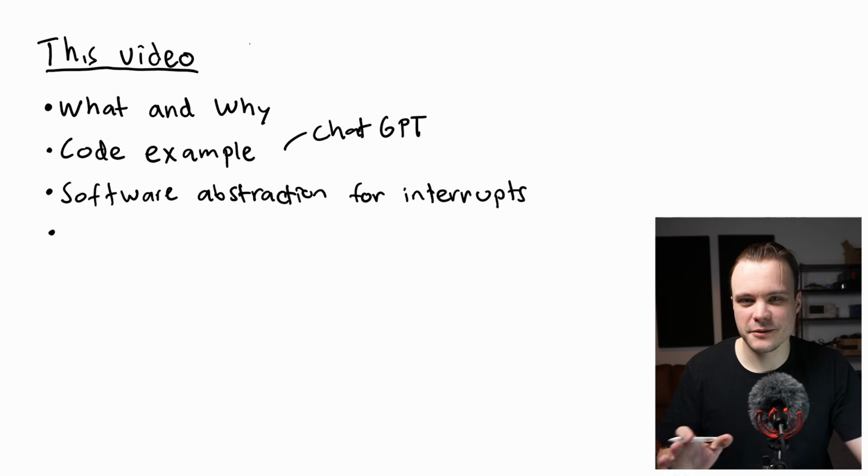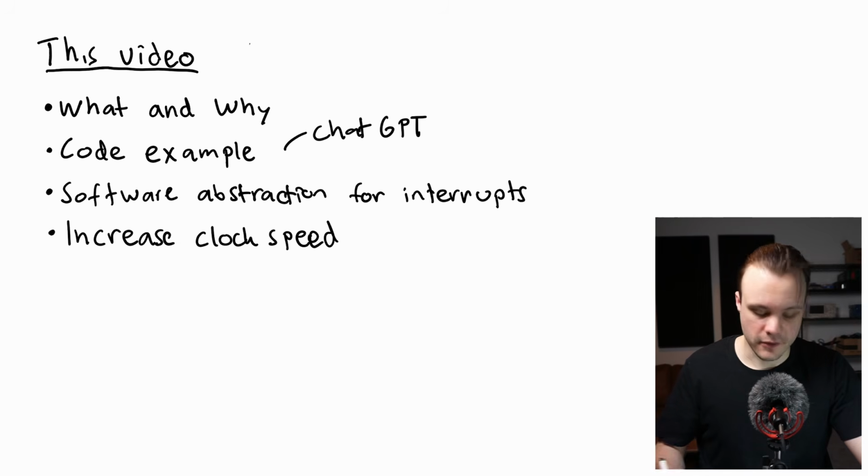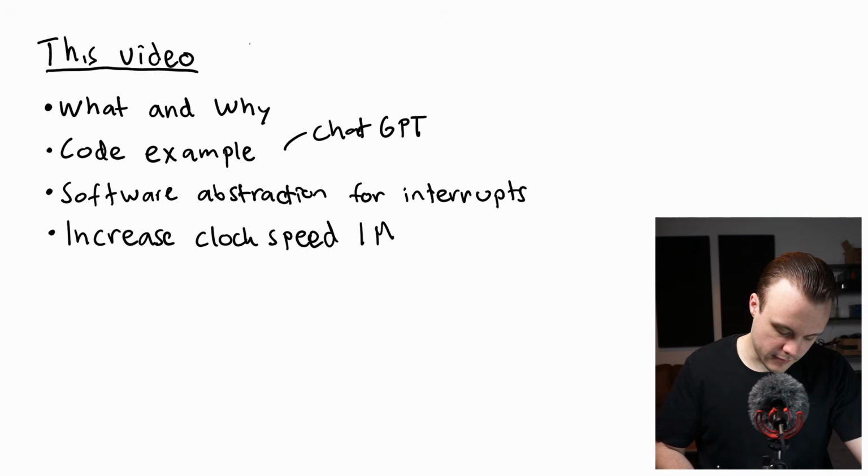And finally, I will take the opportunity to also increase the clock speed of my microcontroller in this video, because currently the clock speed is running at 1 megahertz, and I want to increase it to 16 megahertz, which is the maximum for this microcontroller.